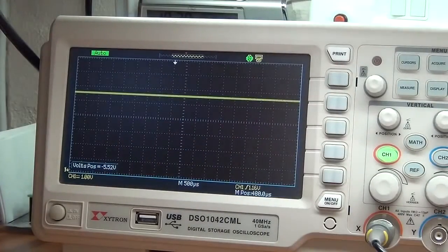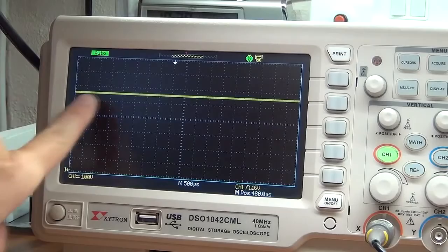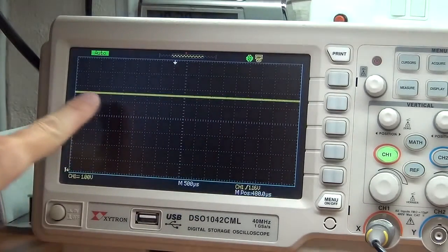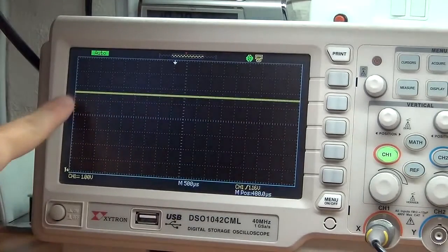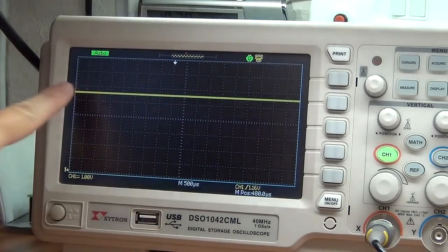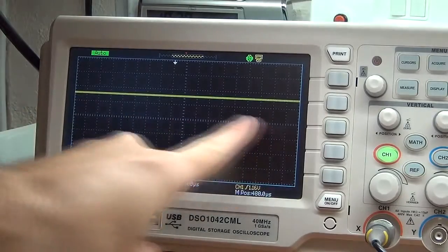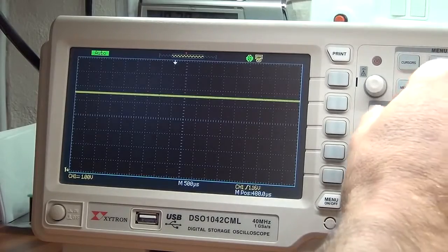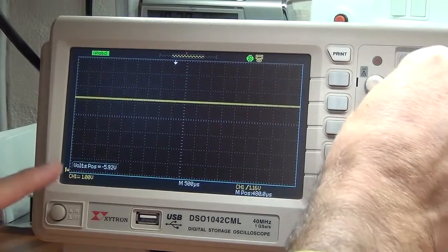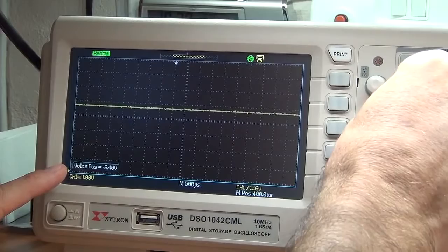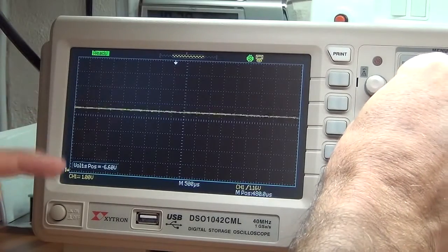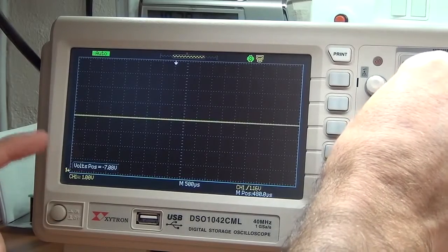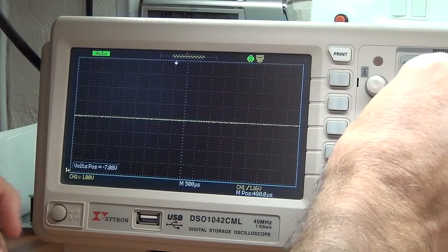And as I showed you on that diagram, this is what a multimeter would represent as a reading if you put it across that battery. It's a straight line because the value is not changing, so it's simply a straight trace across the screen. Now as I bring that down, you'll see there's a volts position, and it's showing negative because in essence the 0 point is being moved down as I adjust the vertical position.